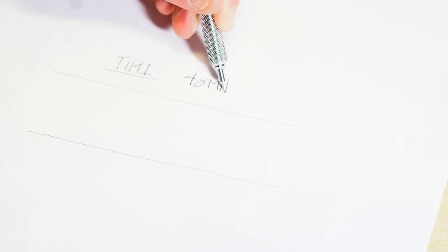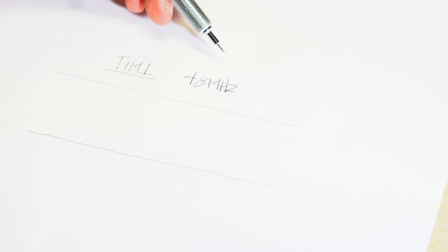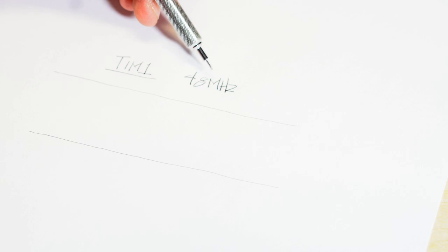To verify that the microcontroller is actually running at 48 megahertz, I'm going to use the timer. And the timer works like this. The timer will use the internal clock, and I'm going to use timer 1. This is how we'll be writing it in code, timer 1. And the timer 1 will be running at 48 megahertz, unless we prescale it or divide it down. I want this variable that we just created to tell me when 1 second has elapsed.